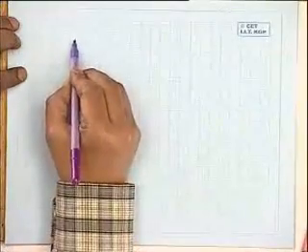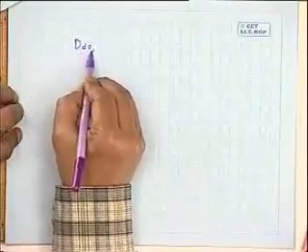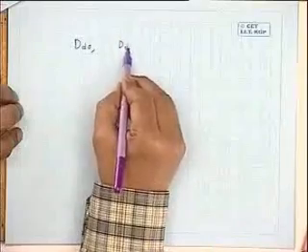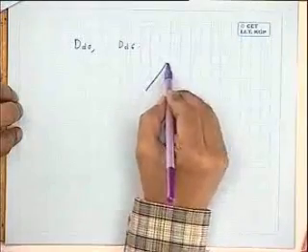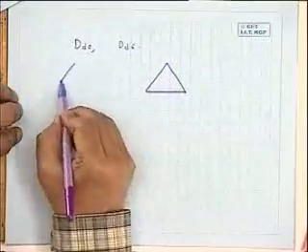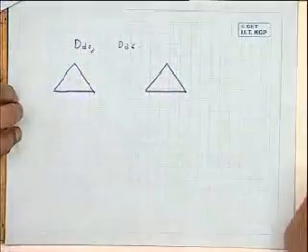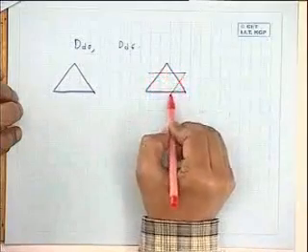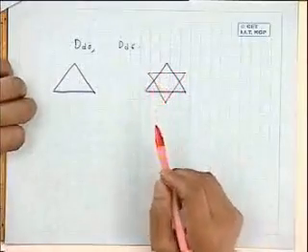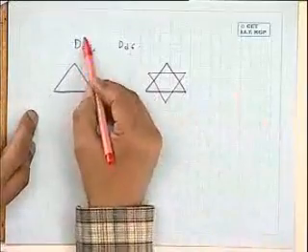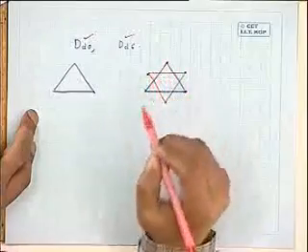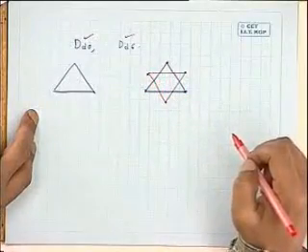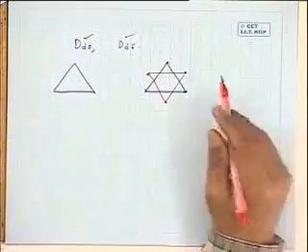Yes, you can get another connection, the delta-delta connection. What you have to do is this: in this case, there are two sets of windings. How will you connect? You connect one set as DD0 and the other, the primary being the same for both, as DD6. So that delta connection you do. Then the voltage phasors will be like this, with respect to your primary voltage. And the other one will be what? Like a star. These terminal markings I am not doing because we have done so many times. You will be able to do this DD0 and DD6. So these voltages available will be a balanced six-phase voltage.